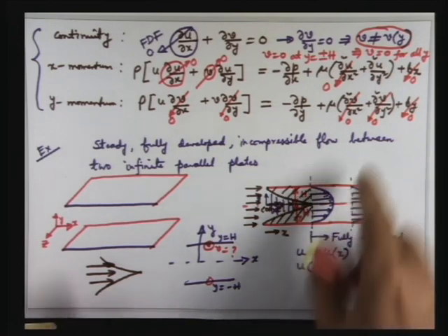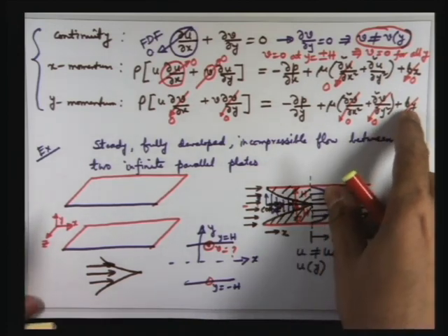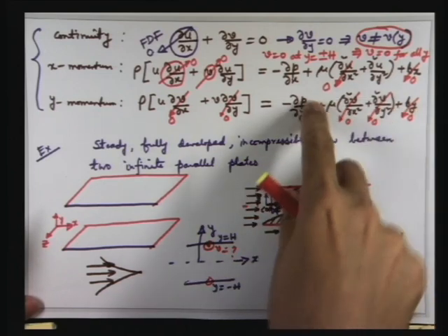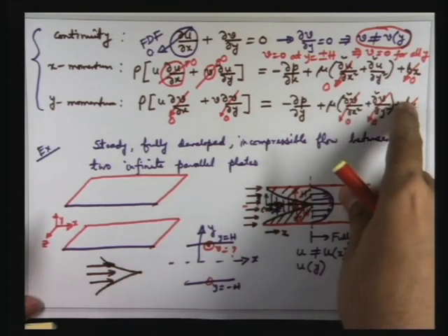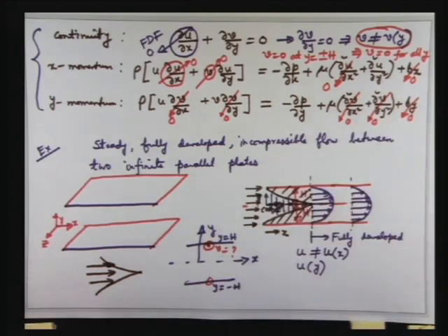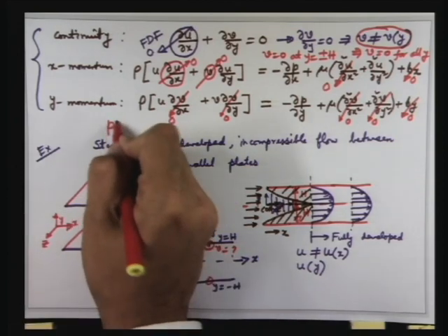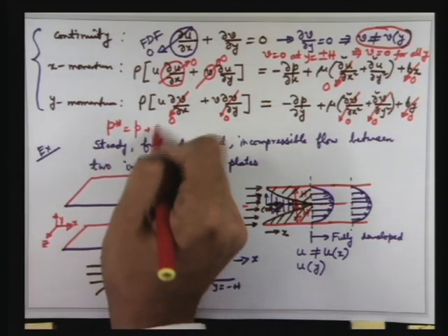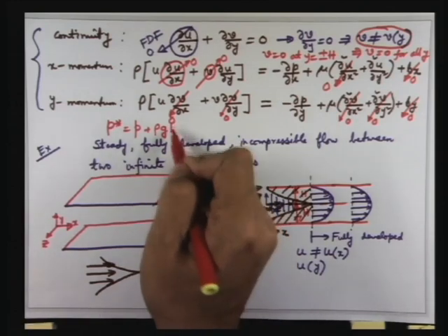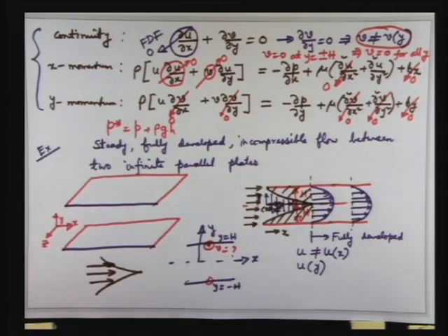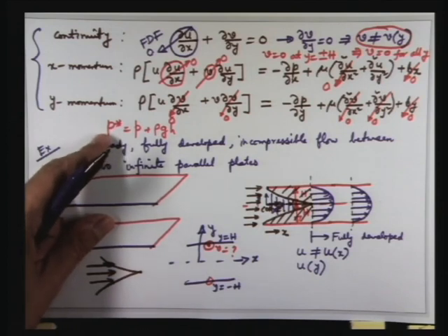So if you have the body force along y as, say, gravity force, then this will give just a hydrostatic pressure variation along y. So you can define an equivalent pressure P star, which is like P plus rho g h, and gradient of that is 0. So this h, or y, takes into account the height. This P star is called the piezometric pressure.